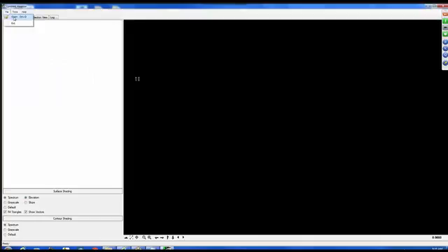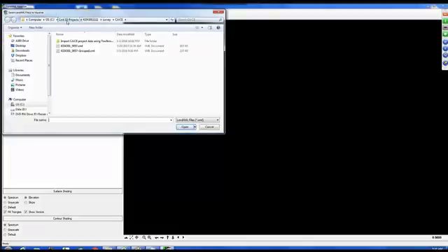I'm going to go to File, and I'm going to say Open. All right? I'm going to go to my Civil 3D project folder wherever it's stored. It could be locally, it could be on your file server, on your network. Okay? I'm going to go into the project, and again, this project was set up by using the FDOT Project Create tool, so it has all the proper directory structures in it. All right? Because the FDOT State Toolkit is very structured: when you're creating a new file, it's looking for a project, and then it's looking for a particular directory to place that file in based upon how that tool is set up. All right, so we're going to pick on this 433431_SR57.xml file. And again, this is the file that was exported directly out of CAiCE. So we're going to select it. We're going to hit Open.